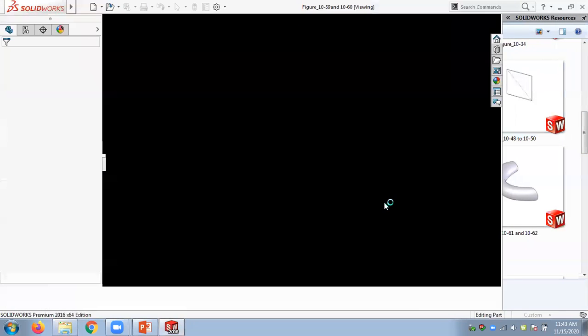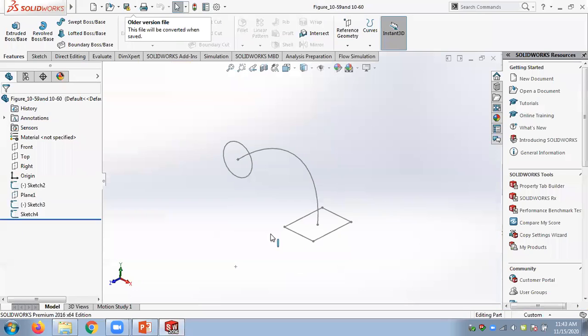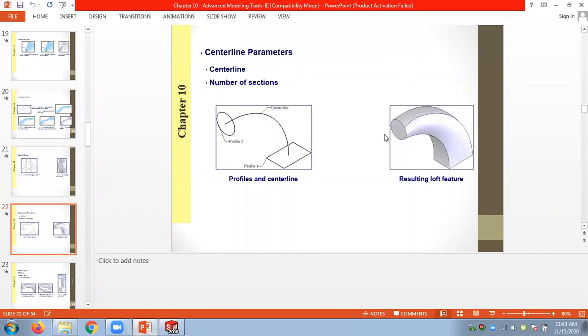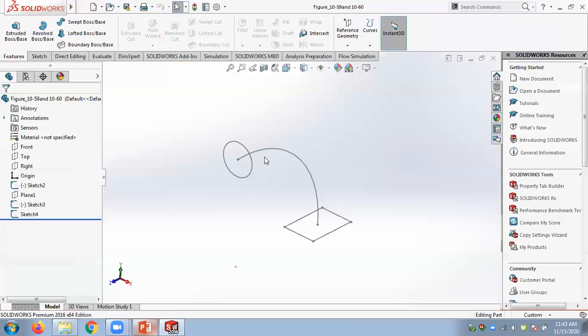Now we have an interesting option. How can I get something like this shape? If I apply the sweep tool, I can only change this profile and take up to here, but the interface is also rectangle. If I apply the loft tool, it's directly coming and hitting me. So I will show you what happens when I apply the sweep tool.